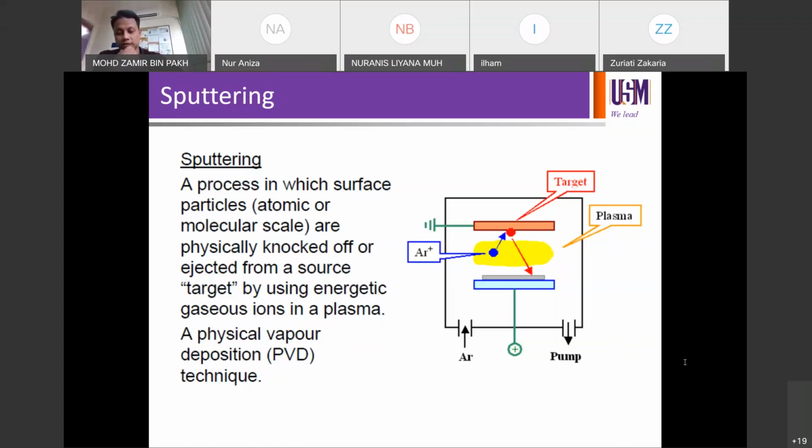So this is the mechanism that you have used last time. It's dislodgement of atoms or molecules. You dislodge the atoms or molecules from their original position, and the original position is in the sputtering target material. So if you're sputtering silicon, then you are knocking off silicon atoms off the target to fly in the vacuum environment to get to the substrate.